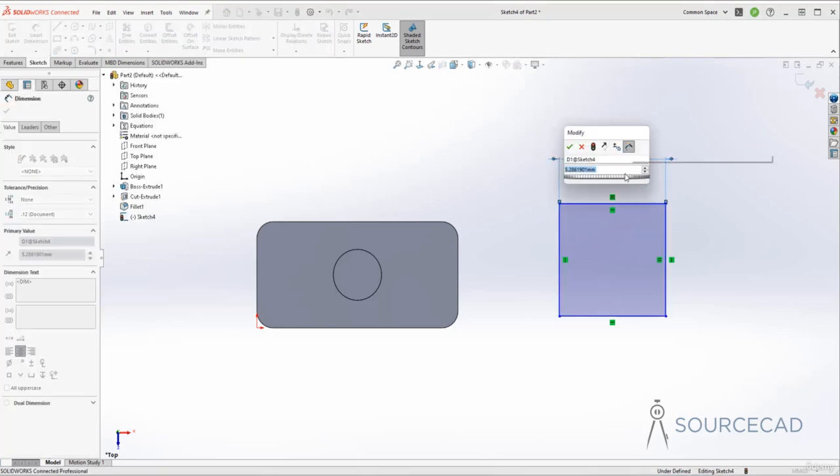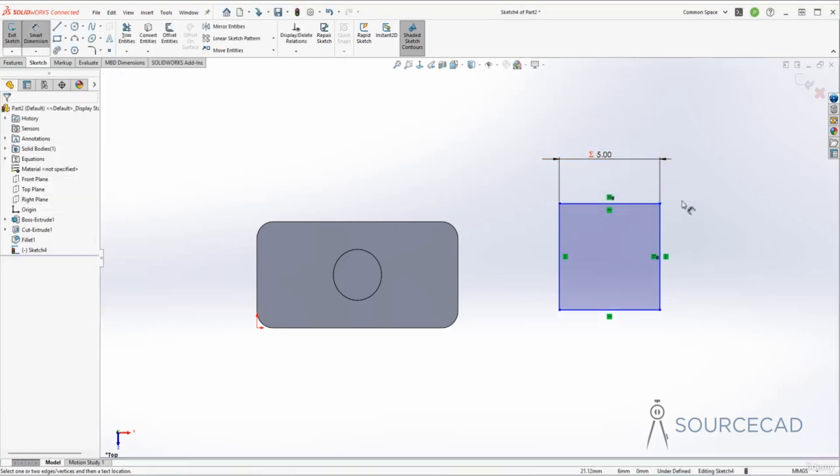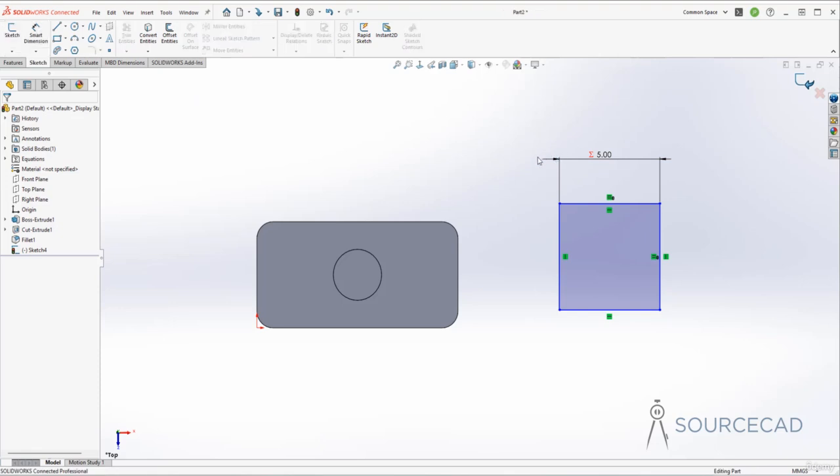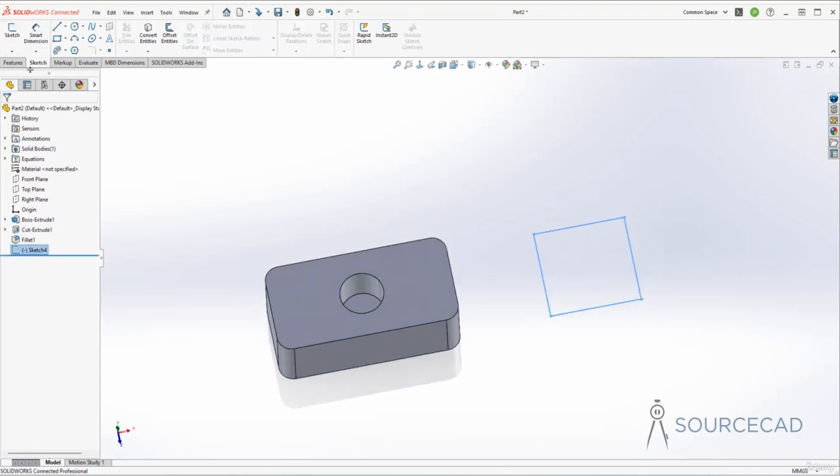And now I'll define a global variable for only one of the sides. Now this one, I'll just make it width. So that should be 5 unit. And done. All right, so that is now defined. Now you also know that this width is 5, so the same width is used here. Now let's exit this feature here, and let's add a height.